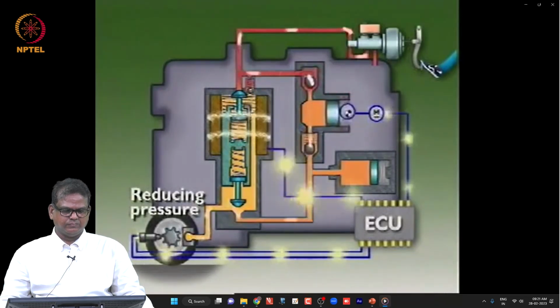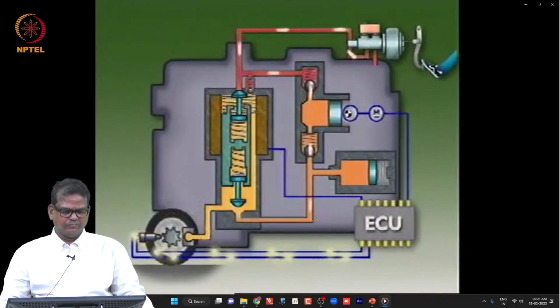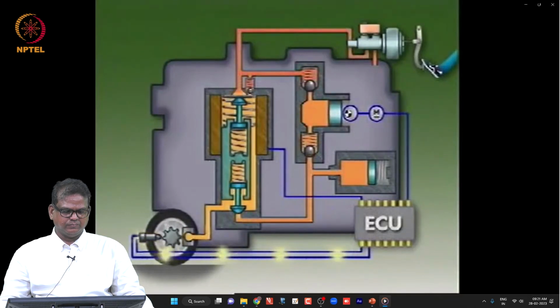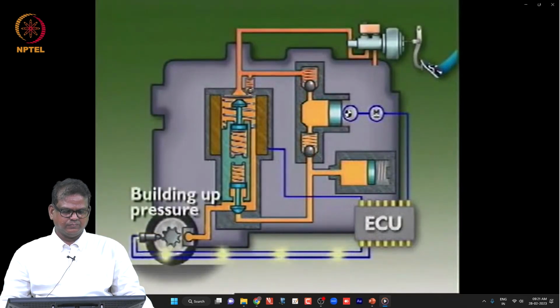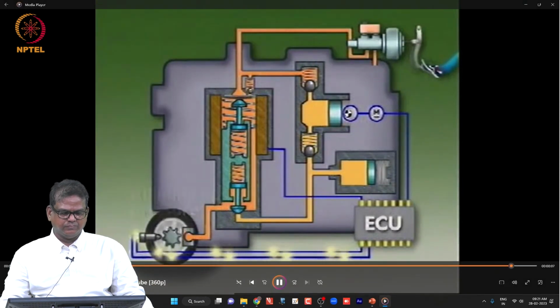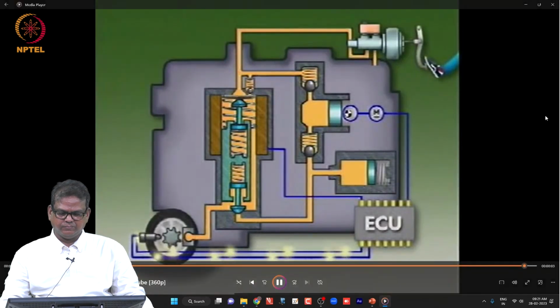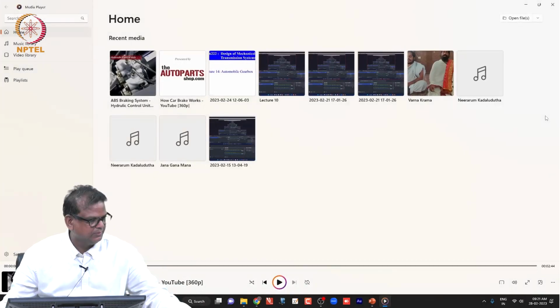If the sensors then signal that the lower pressure has let the wheel speed up, the ECU stops all command current, which de-energizes the solenoid valve. The pressure rises and the wheel is again slowed down. No matter the phase of operation, pressure in the circuit can never rise above master cylinder pressure. So this is the way the ABS brake system works.